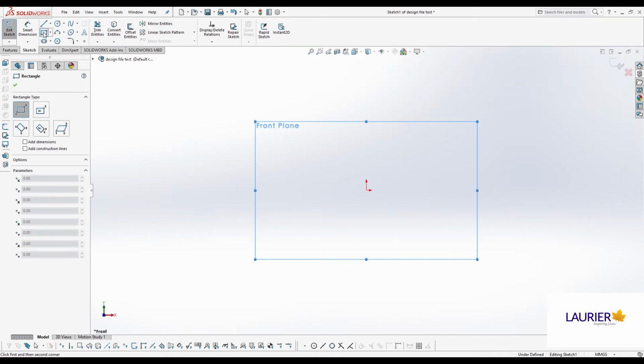And we'll bring our cursor down to the upper left portion of our drawing window. Let's take a look at our cursor. It's no longer a triangle like it was earlier. Now it's a little crosshair on the 2016 version of the CAD, and it's a pencil on the 2019 version of the CAD. So your pick point, instead of being the tip of the arrow, is now the center of the crosshair on the 2016 one, or the tip of the pencil on the 2019 one.